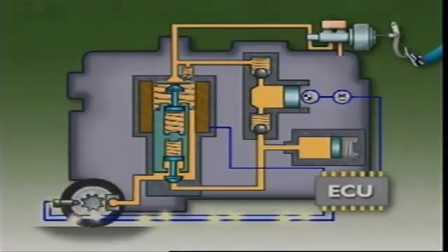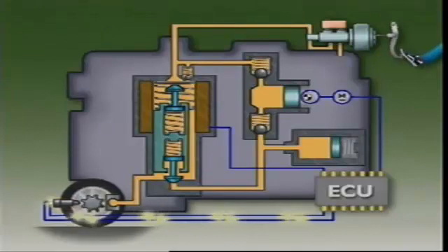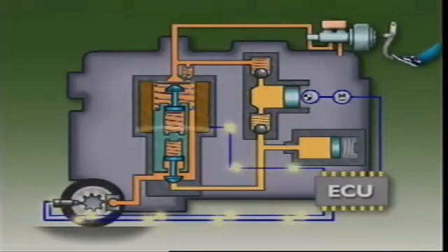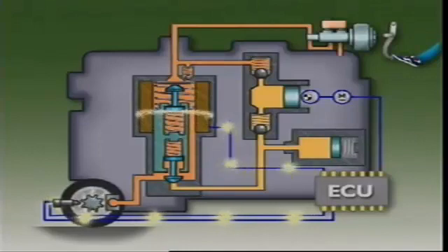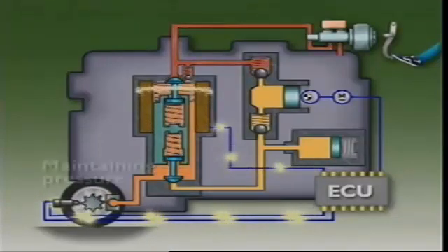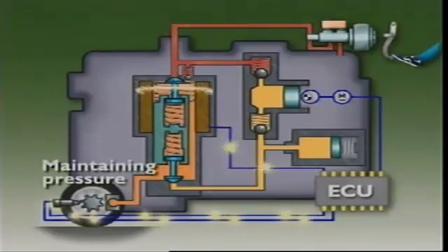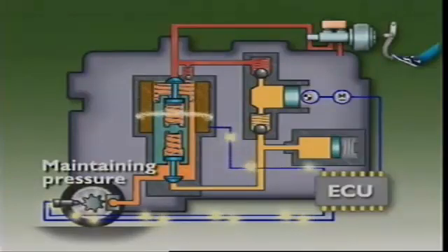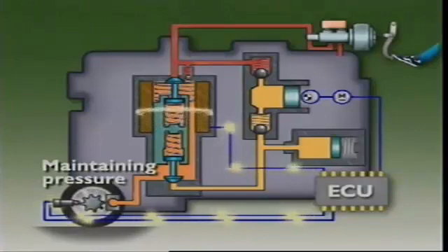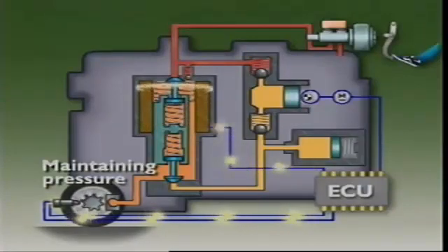When the control unit detects any lock-up tendency, perhaps from too rapid wheel deceleration, it sends a command current to the solenoid coil. This causes the armature and valve to move upward and isolate the brake circuit from the master cylinder. That keeps the pressure between the solenoid and the brake circuit constant, whether or not the master cylinder hydraulic pressure rises.